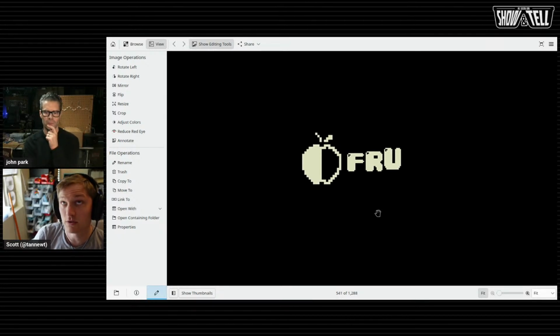The way the DVI output works, there's this big buffer that is the picture, and it's just looping over that, spitting it out at whatever frame rate we want. Then displayio is trying to update at the same frequency, but often if it slows down, it doesn't always do that perfectly. They're not locked together. So that's why we're seeing artifacts like this.